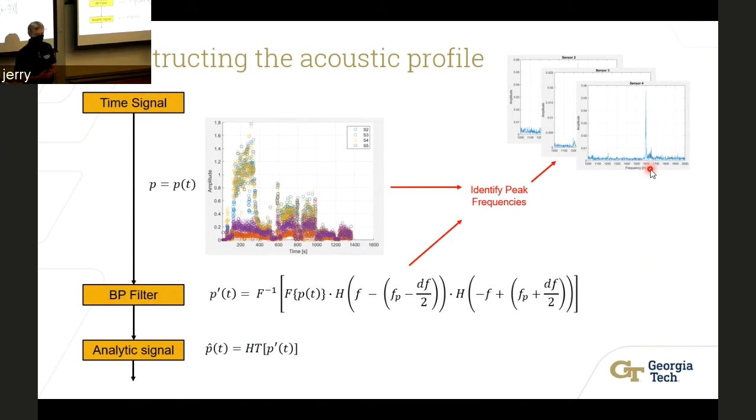What I mean by that is we started off with 200 hertz without seeing these amplitude frequency plots. And as a result, we were capturing this smaller peak because it's between 1600 and 17 hundred hertz.